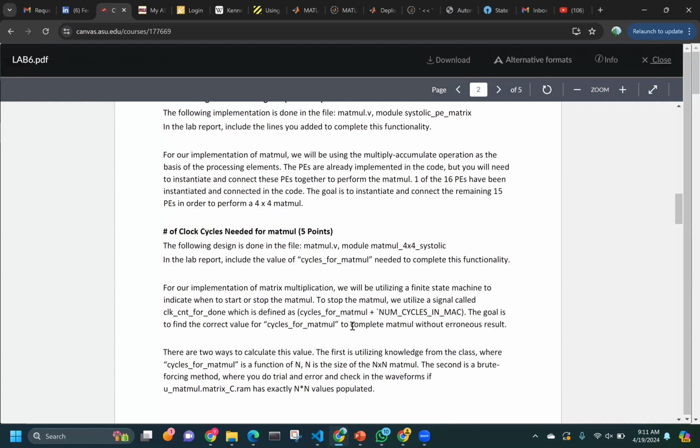You definitely understand how a shift and add multiplication works. When you multiply two numbers, you take one bit from the second number and multiply the whole of the first number, and essentially you generate some partial products that way, the shifted versions. Then at the end you add bit by bit each of those to give you a product term, which is definitely in larger bit width than your operands. That is what is happening in systolic fashion in the array. So only after n clock cycles you will see the final result. What that n is, is something that you have to observe from the test bench and mention in your report.